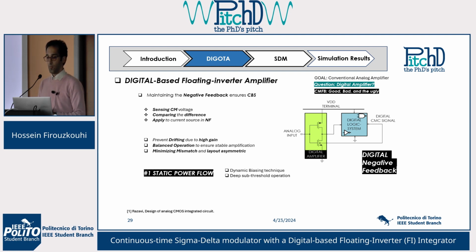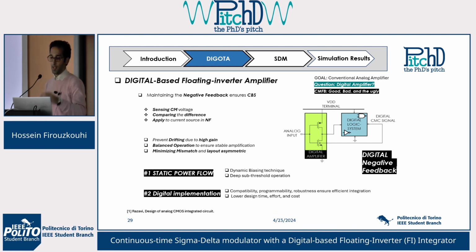Since in this concept we use the dynamic biasing technique, the current flowing through the VDD to ground is minimized, and especially the transistor is working in deep subthreshold, in the order of nano-ampere. And the digital implementation has many benefits and ensures integration, and also in this way we take advantage of lower design time, effort, and cost.